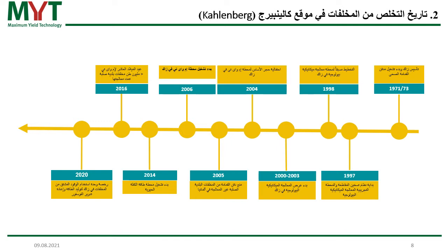If you're looking for a process or for a treatment plant for Egypt, please check if the proposed system is already running in the world. You can only rely on processes or systems which are proven and which have shown already that they can run at least 8,000 hours per year. So this is 11 months of 12 months. You shouldn't have more downtime, and you shouldn't have more maintenance time for a waste treatment facility. This also applies to incineration facilities. 8,000 hours per year. You should be able to process your waste, and you should rely on your facility.